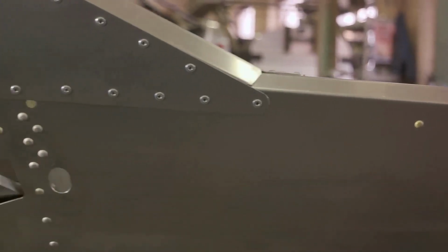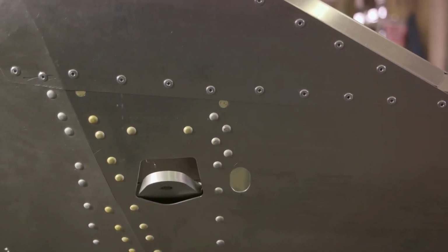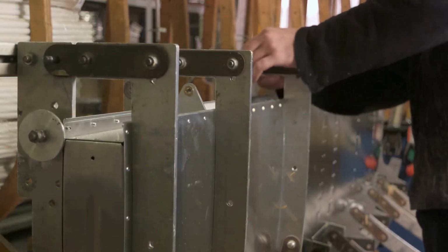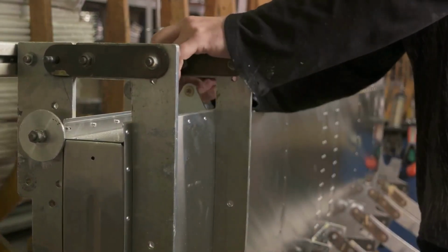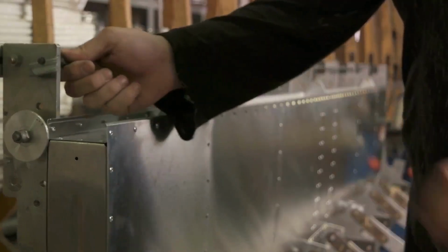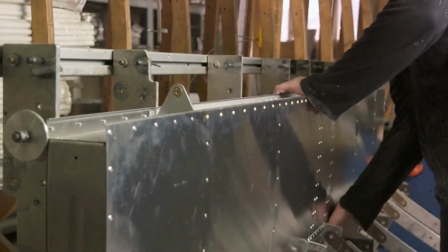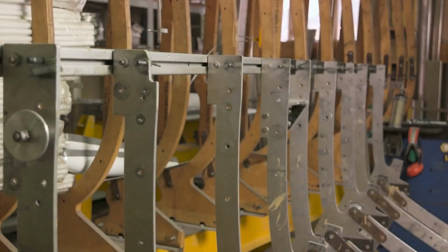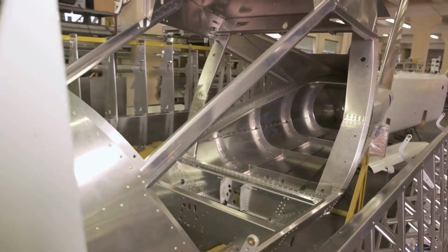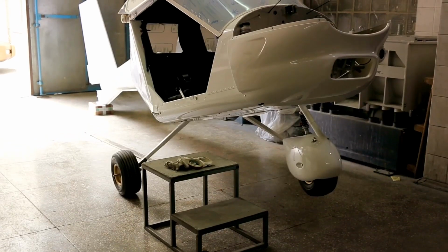Diving headfirst into the manufacturing process, let's begin with the fuselage. The fuselage, or the aircraft's main body, is an engineering marvel in itself. It's primarily constructed from high-strength aluminum alloys, crafted into a cylindrical shape to withstand the pressures of flight. The manufacturing of the fuselage involves forming, cutting, and assembling large aluminum sheets. These sheets are first shaped by a process known as stretch forming, then cut into precise shapes by automated machines. Once cut, these pieces are fastened together, using thousands of rivets and fasteners, creating the basic structure of the fuselage.